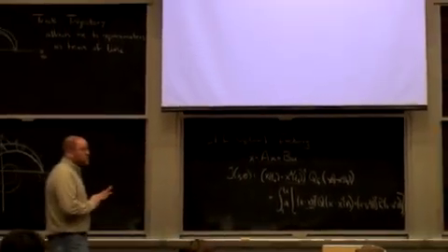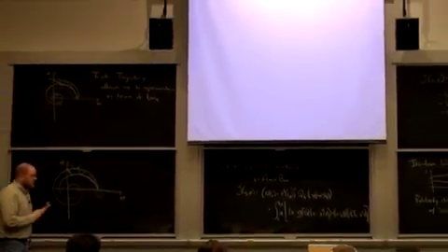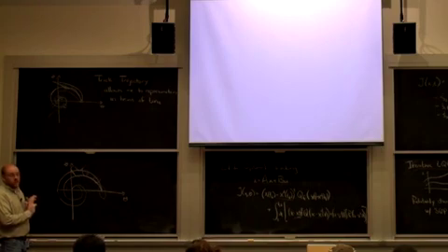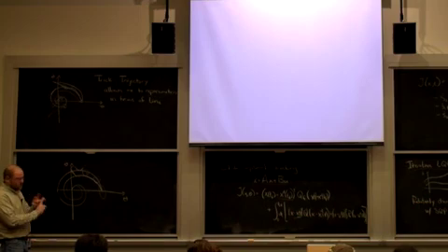So on Thursday we get to do walking robots. We're going to move on to the next major thing. But you've now learned the open loop trajectory optimizers that people really use: iterative LQR very quickly, RTRL, backprop through time, which I grouped as one, the shooting methods, and direct collocation.